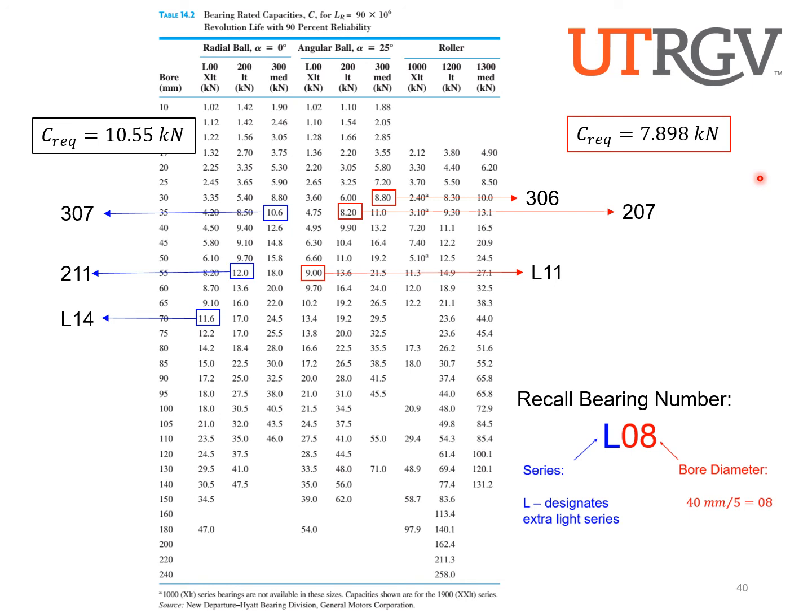But that's generally the process. The only thing that we skipped here, for the sake of saving time, is doing the statics to figure out the reactions at the bearings. Once you have the reactions at the bearings, this is the process that you would follow. Again, here we've solved for what size of bearing we want, so that's the capacity. The other equation has all the same factors that we pick in exactly the same ways, but in those cases we would be solving for an L, which would be a life in revolutions, given a certain size or capacity of a bearing.